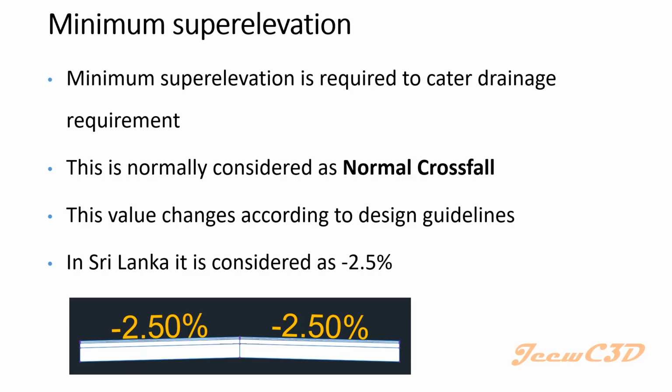It cannot be retained or stay on the road until it dries out. So the minimum super elevation is selected to cater to the drainage requirement.